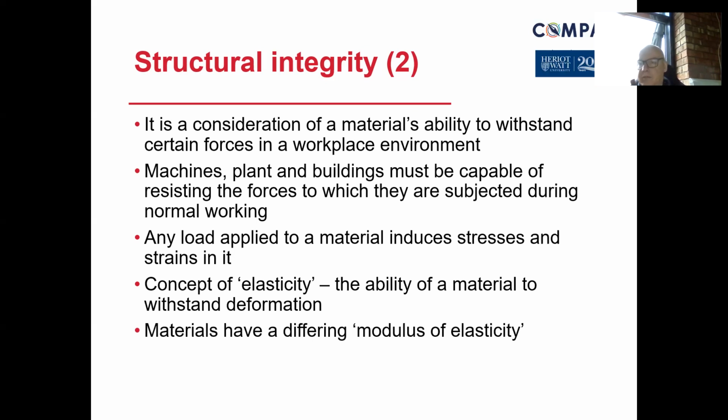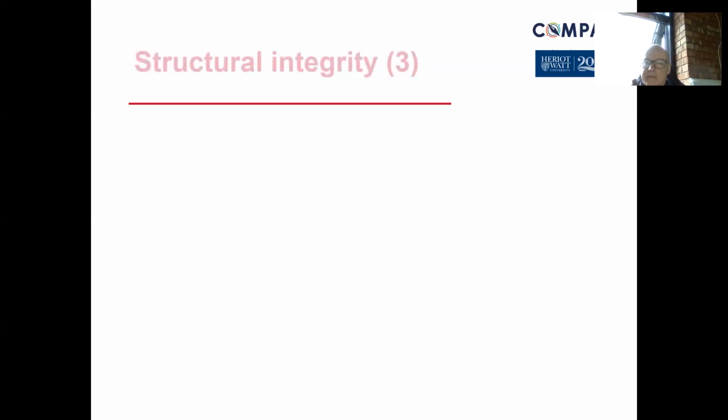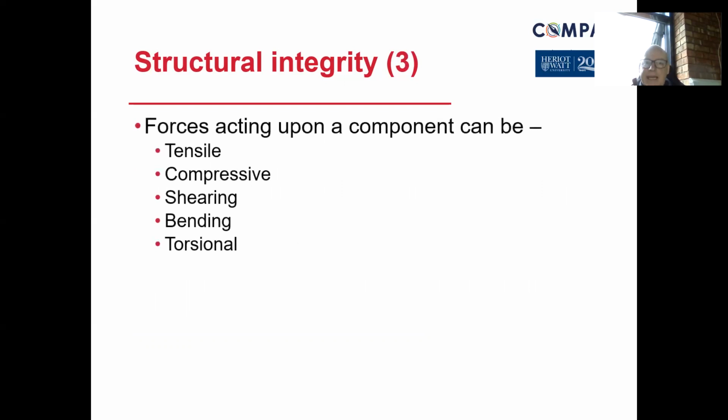So we know this from years of research, mechanical engineering and so on, and it can tell you basic information of what it's capable of withstanding. It puts these various materials on these tests to check what it's capable of reacting to. So it's tensile strength, it's compressive strength, it's shearing strength, bending and torsion strength. So in order to do that, it proves integrity. That integrity affects reliability. As a result of that, you can then say that material can be used in this process under these strains and stresses, and should withstand what I class as a safe working load.